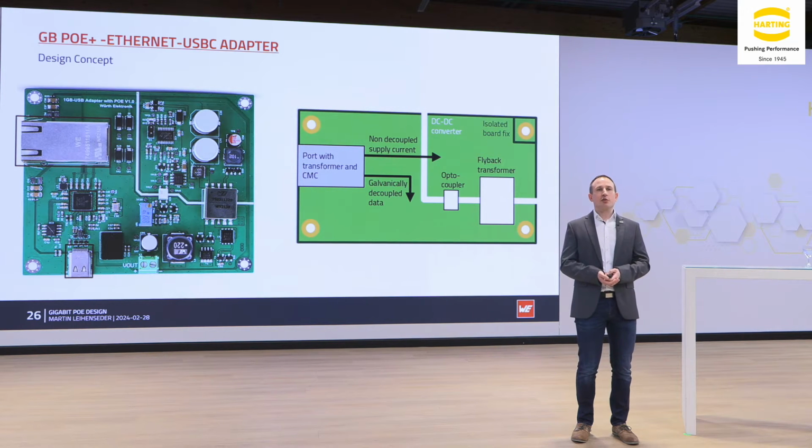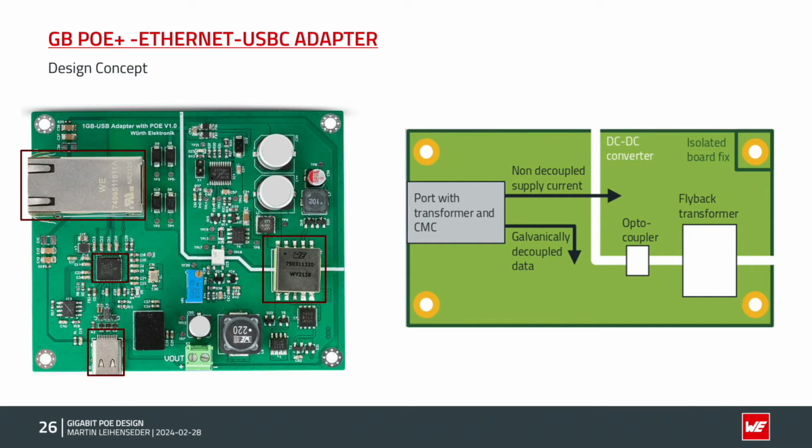This is the USB connector, so this is the path for the signals, and the power is going another path. You can see here a power transformer. We have up to 47 volts with PoE, and this transformer transforms this into 6 to 18 volts, providing a power of up to 25 watts. So this is a PoE plus system.